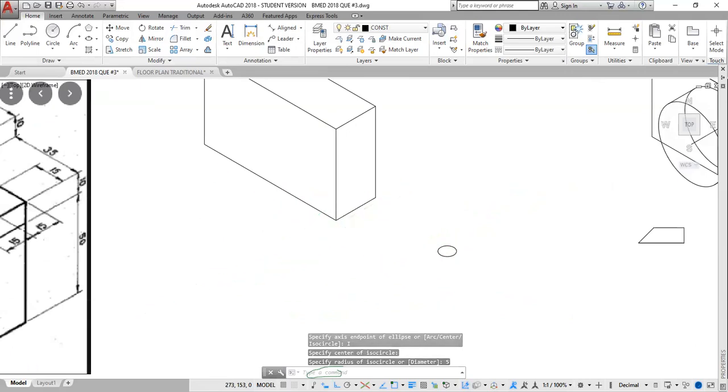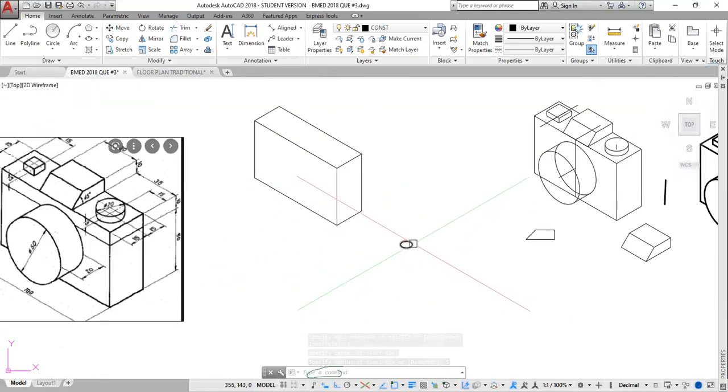The next step is, we have the base for this, but we want a height for this. This has a thickness of 5. So I'm going to change from my top face to either my right or left face. For that, I hold the Shift key, then press F5.